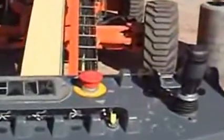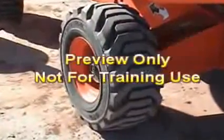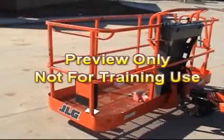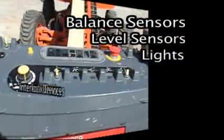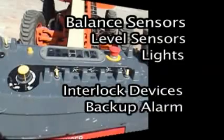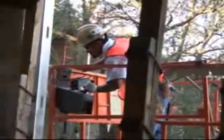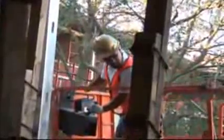Emergency stop buttons should work correctly. Tires must be properly inflated and inspected for damage. All safety guards should be checked for malfunctions. Check balance sensors, level sensors, controls, lights, interlock devices, backup alarm, and intercom for proper operation. The emergency descent system should be checked by raising the platform a couple of feet and then turning the lift off and using the auxiliary power to lower the lift.